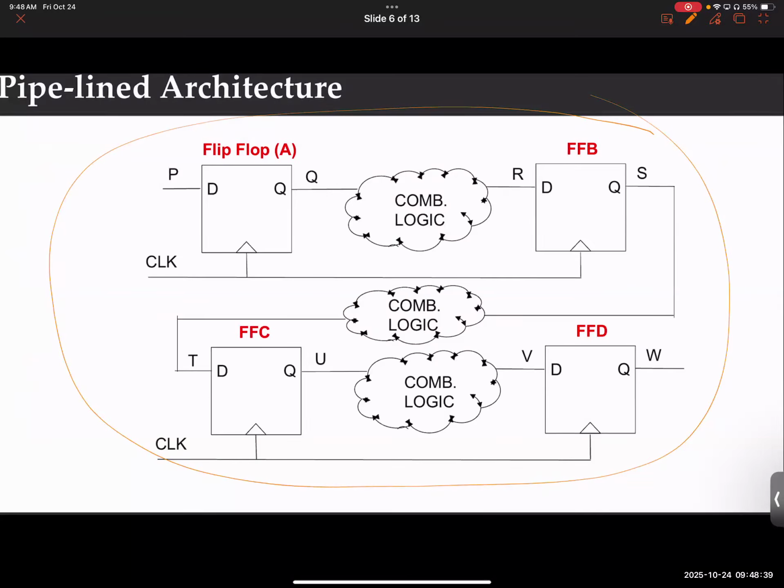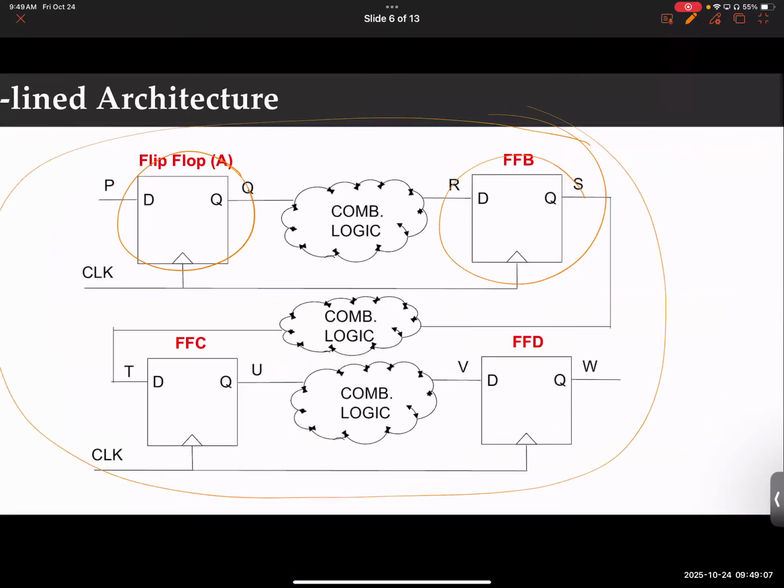You have flip-flops before and after combinational logic, and this is called a pipelined architecture, as if you're going through a pipeline. And these flip-flops are flow controllers. They're synchronizing elements. Without them, your system will not work, because you will lose track of the meaning, honestly. You have millions of bits and none of them have any meaning, just ones and zeros, unless you keep track of the numbers of the bits with the flip-flops. That's how critical these are. Okay.